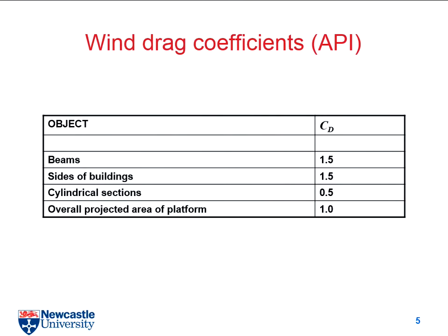And even afterwards, if you do an experimental study, for example in a wind tunnel, I believe you will have another different result from the result in CFD. That's also quite normal. So you can only carry on, and at this stage we trust the result from the experimental study. But after you build the structure and use it in open sea, this time you can measure the forces. Then you can go back to the estimation here and correct your rules and correct the drag coefficients. That's the reason why it gets better and better. But by this stage, when we do estimation, we just use it. Okay? So I think the wind force is clear now, right?